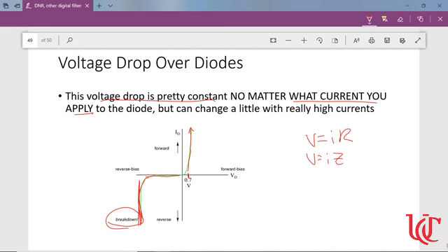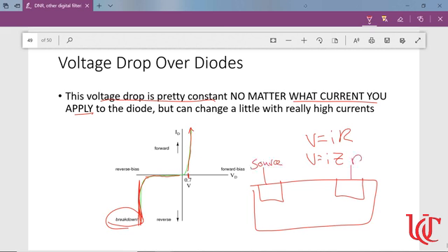Okay. It's very similar, although the values are different, with our transistors. Again, I get a source connection, a drain, and in the middle I get my gate. In theory, we said if this was N-doped, P-doped, and N-doped, that I needed to apply a positive voltage to my gate to, again, overcome those negative charges that would build up in the depletion zone of that body.